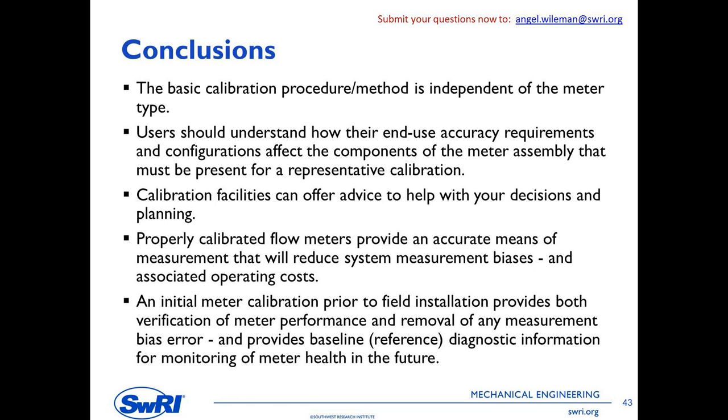Okay, so conclusions here. Hopefully you see that the basic method is independent of the meter type. You need to understand your end-use accuracy requirements, understand how much of the meter assembly you need to ship to the lab, assuming that's what you're going to do. Keeping in mind calibration facilities, this is what we do for a living.